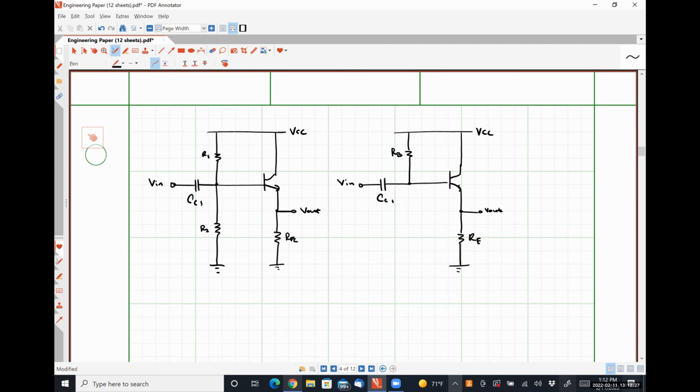So what we would see is effectively our input voltage applied directly at our base, our output voltage taken at our emitter, and between base and ground, we would have R1 in parallel with R2. Is that going to change the input resistance of our core common collector amplifier?